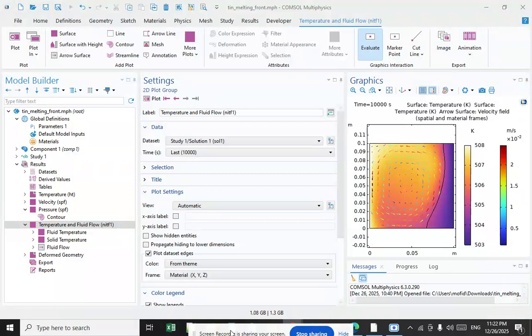A monotectic reaction consists of change from a liquid to a combination of a solid and a second liquid, where the two liquids display a miscibility gap. Separation into multiple phases can occur via spinodal decomposition, in which a single phase is cooled and separates into two different compositions. Non-equilibrium mixtures can occur, such as in supersaturation.